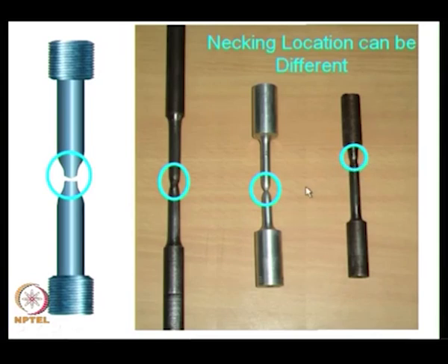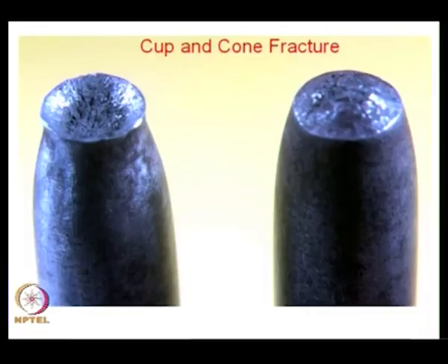Since you have seen what really causes necking, you are in a position to appreciate that internal flaws dictate where necking would precipitate. So, you can understand it can happen along the length of the specimen. My focus is to appreciate the shear lip in the case of necking also, we would have a look at it.